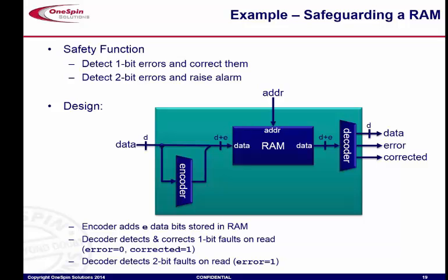The typical thing here is the classic 2-bit ECC. So you detect and correct 1-bit faults. You may even flag the corrected faults so that it at least gets recorded in your chip that there was a fault, but it was corrected. And you're still able to detect any 2-bit faults. So in this case, the data is corrupted, and it's really crucial that some specific error handling mechanism is triggered.